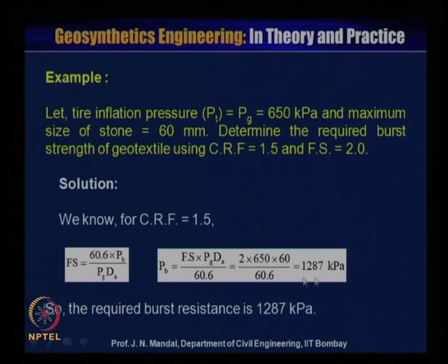So, it will give 1287 kilopascal. So, the required burst resistance is 1287. You can see for this pressure you can have this 1287 kilopascal burst strength.